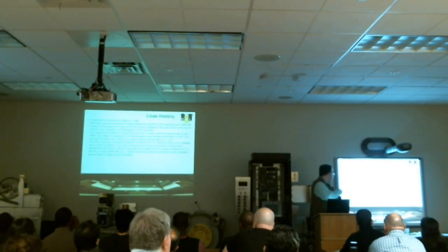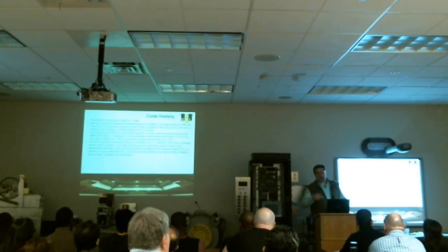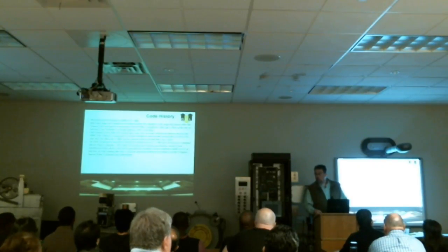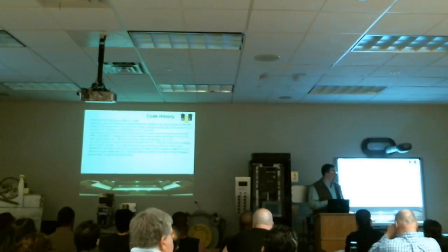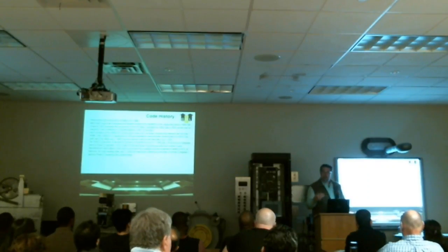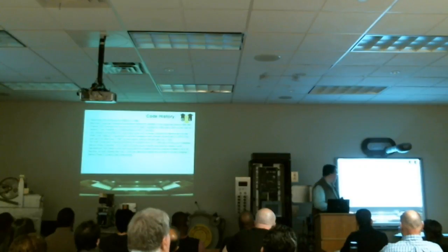When they adopted the 2008 code for door lock monitoring for New York City, they wanted it to work except for fire phase 2 operation. Okay? Now, fire phase 2, maybe for some of you who don't know, that's when the fireman actually has control of the elevator under a fire service emergency condition. That's the fireman who is able to operate the elevator independently, in an emergency evacuation procedure.